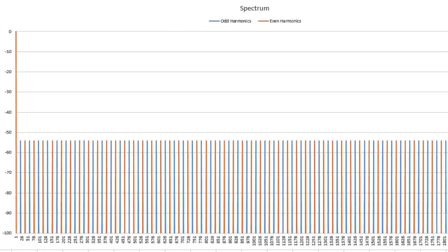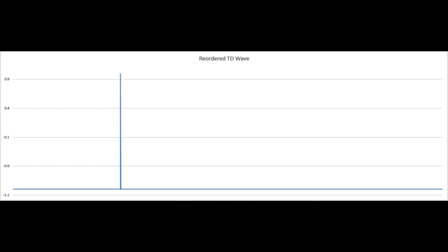The peak is so narrow and so small, even if it's gigantic, and you're limited. Let's remember, most devices don't take more than a couple volts, 3 volts, 4 volts, maybe 5 volts. But if you want an impulse to really test a filter, you're going to need to have an impulse of like a couple hundred volts. That ain't going to cut it. You're going to destroy something. Most capacitors won't take it.